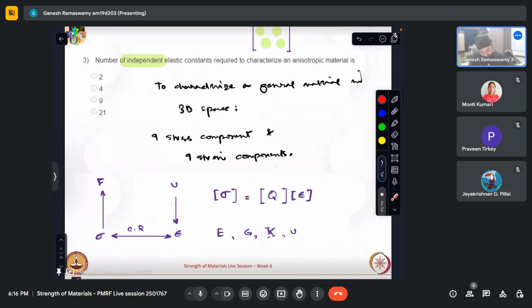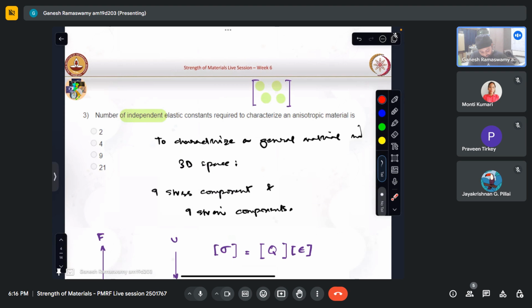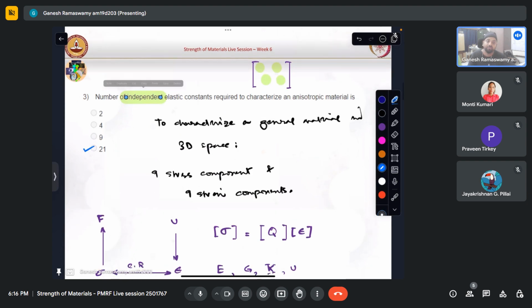component. So for an anisotropic material, the number of elastic constants required comes to 21. This would also include Poisson's ratio in different directions. So Poisson's ratio also will become direction dependent, and there will be coupling, meaning if I pull it, there will be change in distortion also. Not only change in the volume.